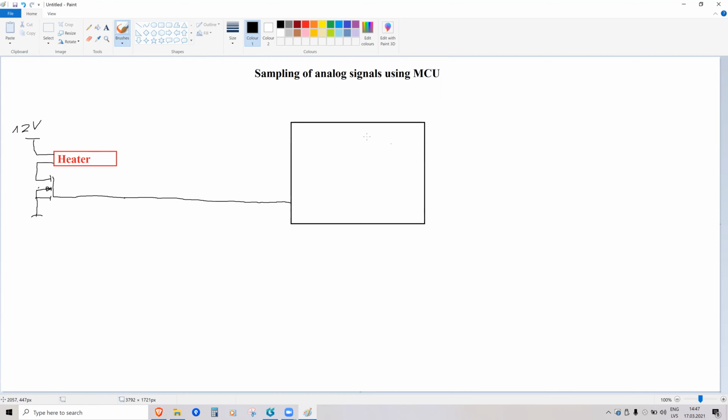Okay, so just to make the circuit complete, if the microcontroller freezes or maybe there's a problem in solder joints, people always put a pull-down resistor between MOSFET gate and source so that the gate is held low and discharged when the microcontroller is off or is in error state, so that the heater doesn't turn on by itself.